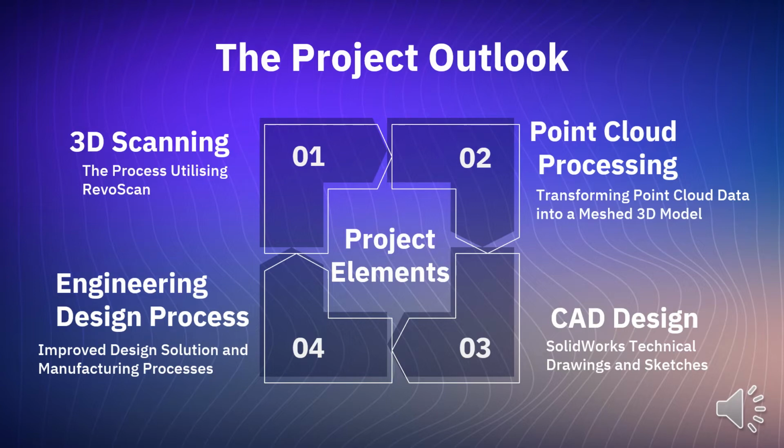The next step is the modelling of the object, where the acquired knowledge is combined and tested in a model. To create a model, we first convert the 3D scan into a mesh model, and then convert that into a CAD model. This can be used to visually interpret the data and make changes. The final stage is review, which includes the testing of the model and its ability to meet its intended use. This is part of the engineering process, which includes improving the design and developing a manufacturing process that is most suitable.